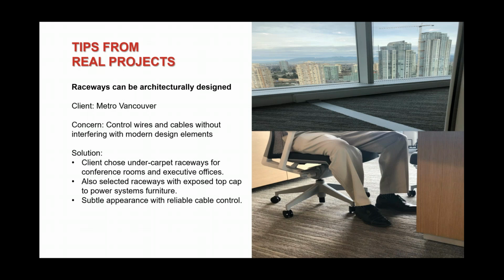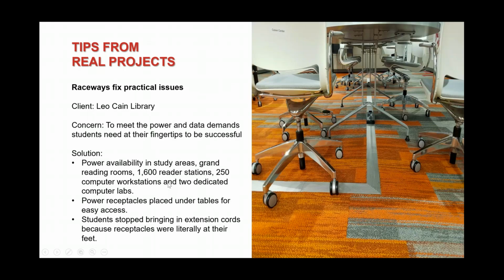And below, they also had in every one of those floors several conference rooms. In the conference rooms, they chose to go with a complete under the carpet system. And you can see him sitting there, the guy with his body cut off. And that is a complete under carpet. They have all the power they need. They have all the data they need. They actually ran an empty raceway next to it under the carpet because it didn't cost them hardly anything. And they said, we're future proofing these meeting rooms in case we want to add something else. So they can be architecturally designed to meet any sort of design that your designer wants or your owner wants.